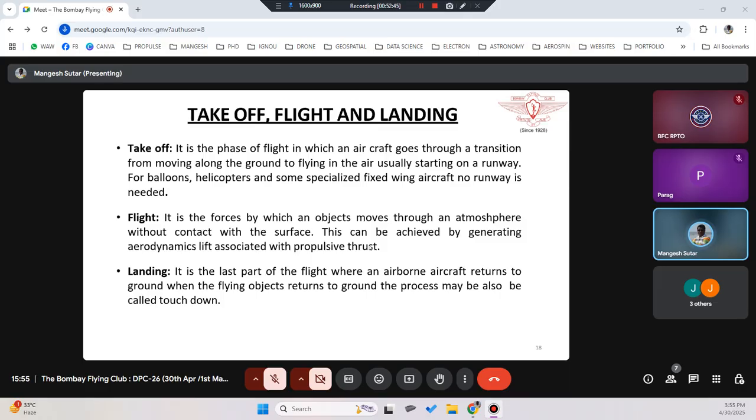Once you are clear on your indications, you might see the battery percentage, the GPS count, and the mode of your flight. Wind speed is also required, so you could see that too. All these parameters you will see, and then you will take a decision to fly the aeroplane or drone. Once you are in the air, your drone needs to be at a level flight. You will maneuver as per your requirements and fly the drone accordingly.